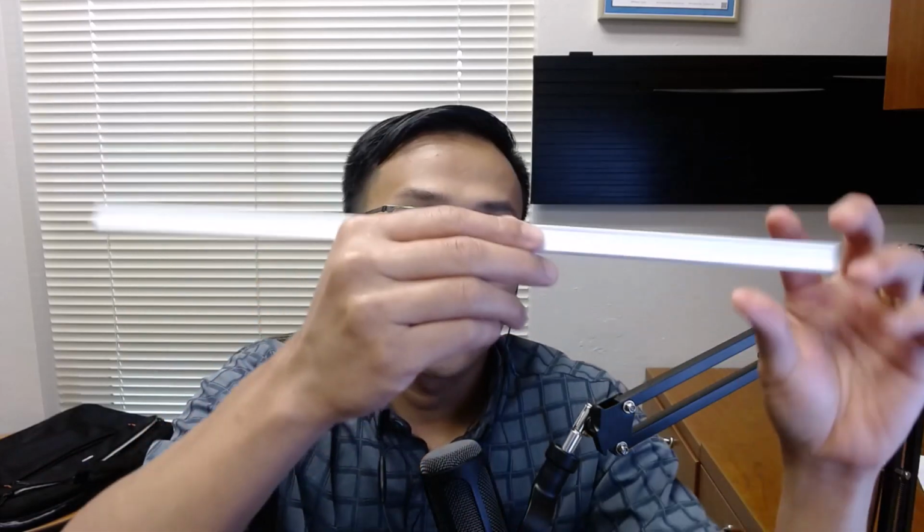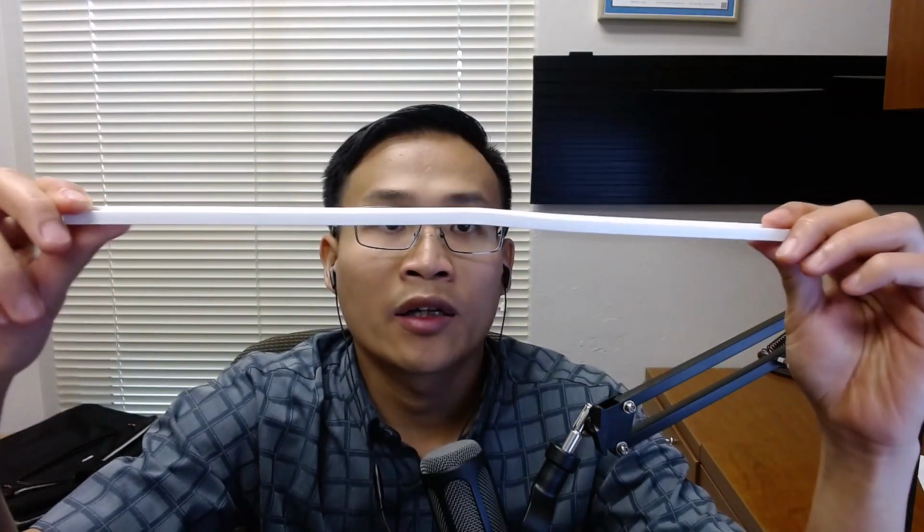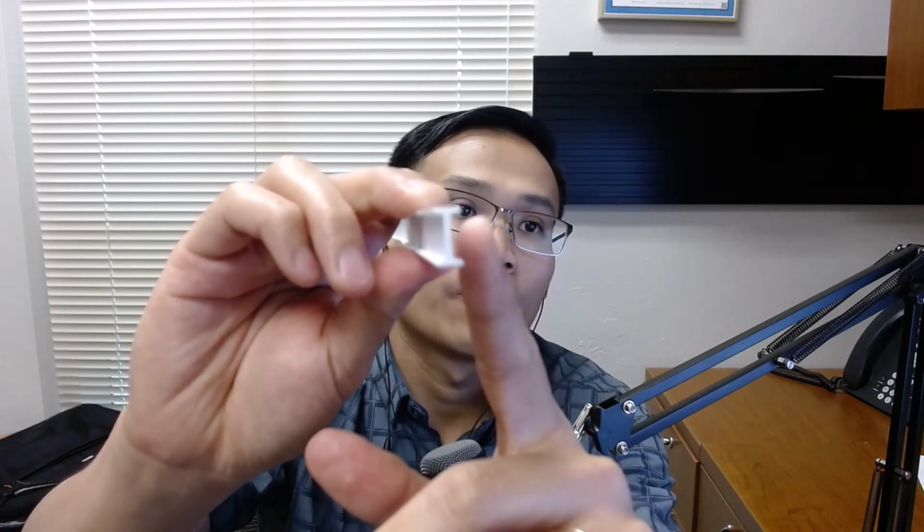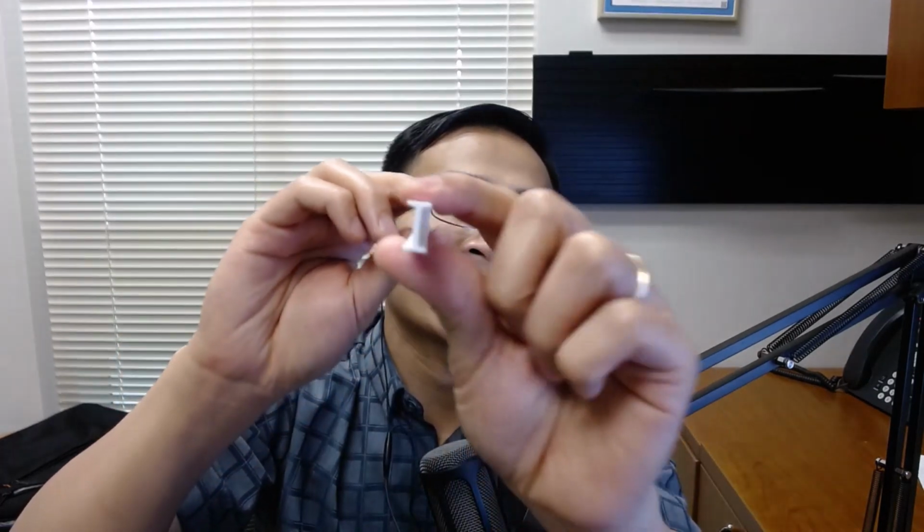So what I have over here is a plastic I-beam. You can see, if we look on this side, it looks like the letter I, right? So we're going to call that an I-beam. The correct name is actually wide flange beam, but in industry sometimes they call it an I-beam as well. For the I-beam over here, they have a y-axis and an x-axis. The x-axis will bend around the I over here.